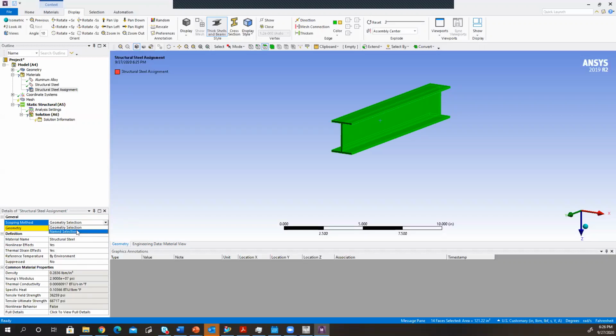If you select the drop-down menu, another thing you can do is name particular parts of your geometry. If this was a more complex geometry, let's say you had a bunch of bolts of the same size, you could actually group them into a selection. Let's say you have 24 bolts in an engine of the same size and material, and you would just group them into a selection, and you would name that selection 3/8 bolts, 24 thread, or something like that.